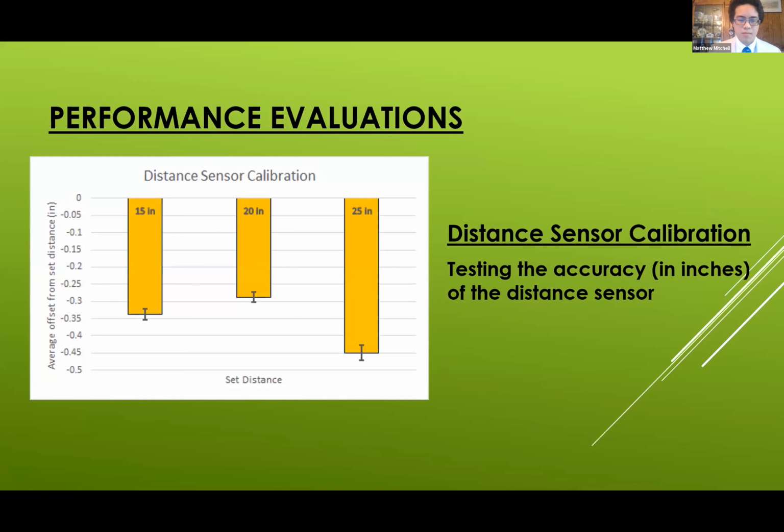In order to calibrate our distance sensor, we devised a simple test in which we took a ruler and attached it parallel to the line of the laser from the distance sensor. We ran an object closer to the distance sensor until it tripped. We did this at 3 different distances and 20 times each, so our sample size is 20, in order to figure out which distances would be the most accurate for a recommendation of where to place the distance sensor and what angle we want it at in order to read.